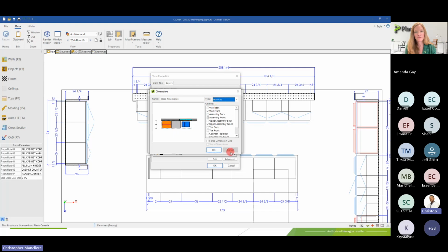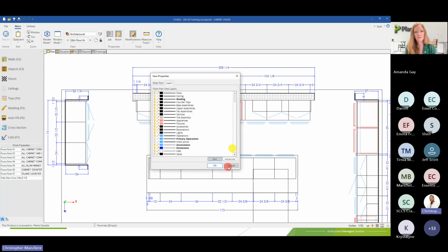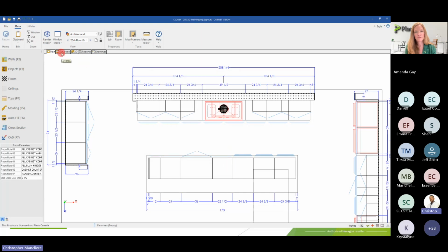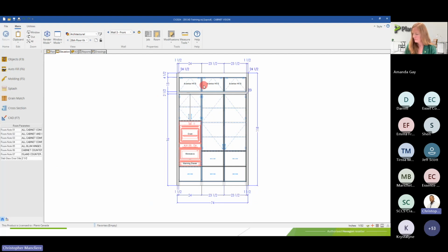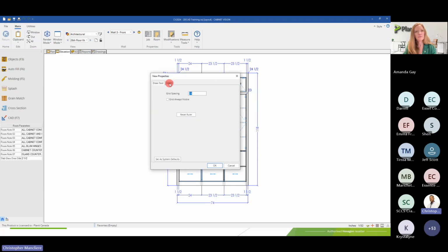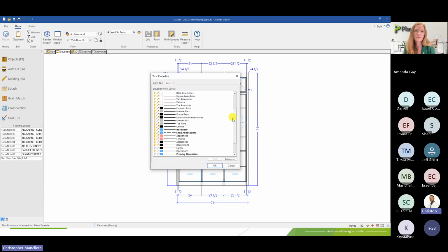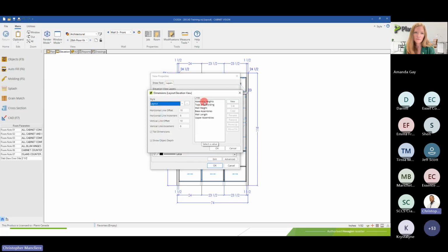So this is for the dimension, and just to also check the same setting in the elevation view. Now the elevation view will have 2 dimensions at the bottom of my wall, one at the top, one on the left, and one on the right. So this is again control just for the elevation view by going in the same screen under layers, edit, and I have 2, 4, 6 lines, which is the total I have.